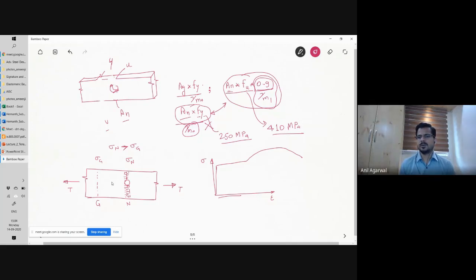Let's say before it reaches the rupture point, it has a maximum deformation of 20%. Sigma U, we are restricting, right? So it will be approximately, let's say, 15%. That is the strain value. So the length change in the member will be approximately 15% of this length.